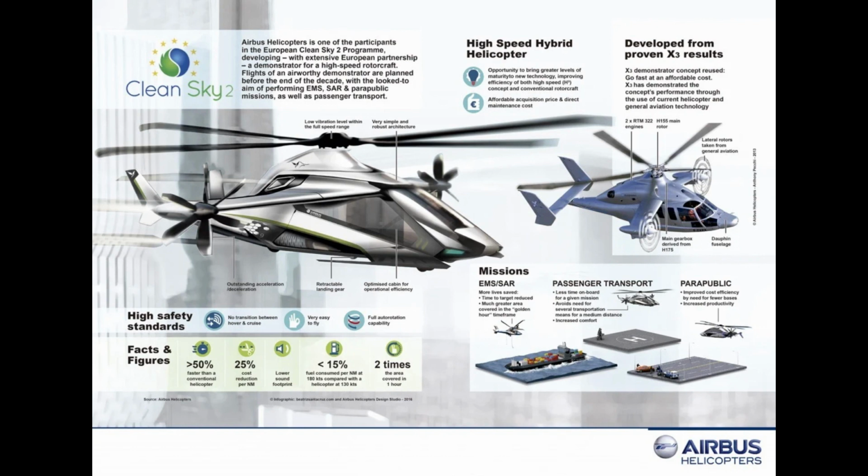Turbine helicopters use a bleed air system for heat. Bleed air is hot, compressed, discharge air from the engine compressor. Hot air is ducted from the compressor to the bleed air heater assembly, where it is combined with ambient air through an induction port mounted to the fuselage. The amount of heat delivered to the helicopter cabin is regulated by a pilot-controlled bleed air mixing valve.